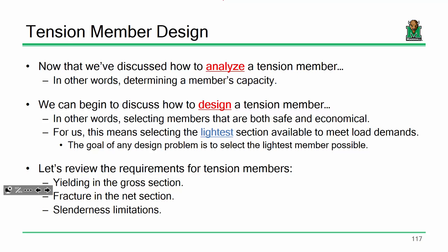All right. Now, quick question. If I have a W10 by 55 or a W10 by 49, which is lighter, the 55 or the 49? 49. And how do we know that? The 49 represents pounds per foot. Okay? So for the problems that we do in this class, we're always going to go with the lightest shape possible.